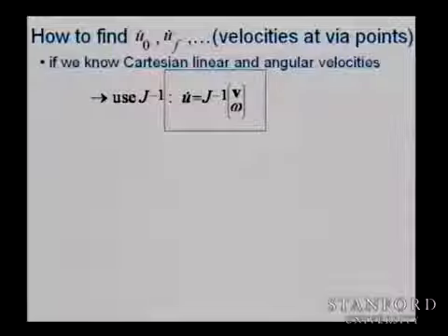So if we say, okay, we want each of the links of the manipulator to have certain velocity, because when you have an industrial robot, they are all targeted for certain velocities and certain angular velocities that are the characteristic of the mechanical structure. You put those in the conditions, you can calculate some target velocities.